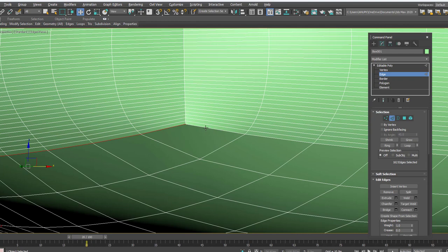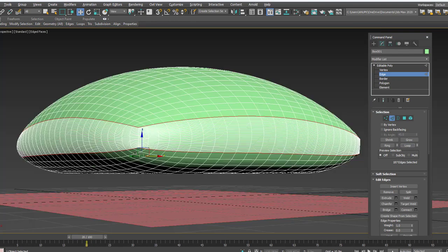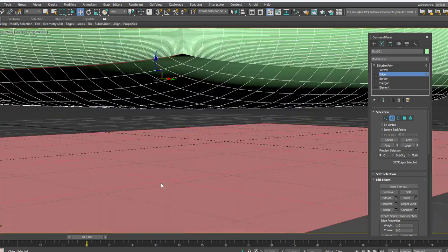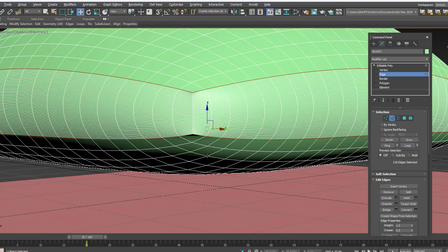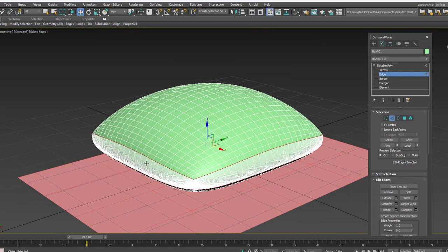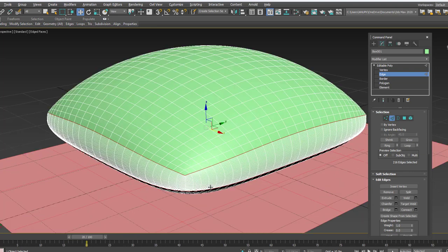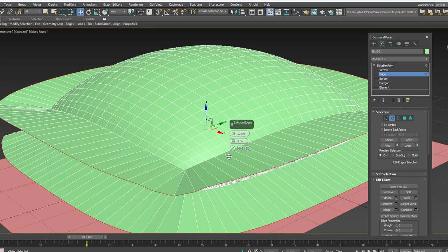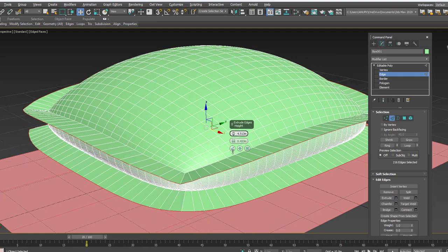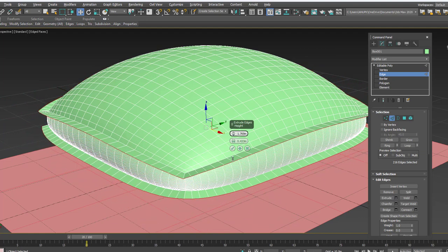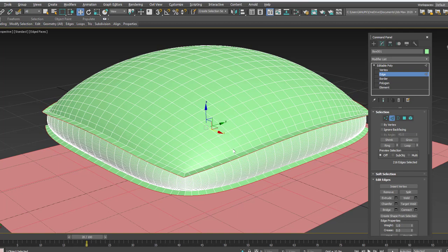Along with this, I want to select, means I have to press the Ctrl, loop, Ctrl select one edge and then click on loop. So I just selected the top boundary line and then the bottom boundary line. For this I just want to apply the extrude option to make it projected like this. So this is how you can add the depth and then the projection amount, a little, and then finish it.